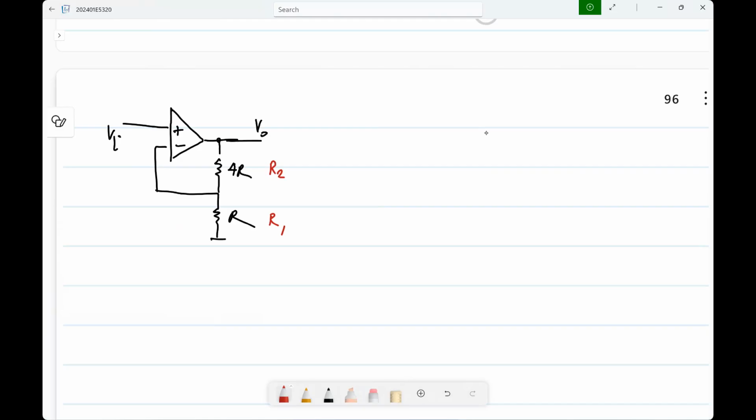No, this won't cause an offset. You can analyze it and see. This will only cause a gain error, right? This is not causing an offset. In the op amp, any mismatch in the transistors will give you a non-zero output current, even if there is zero input voltage. That is an offset. But the error in the value of resistors will not do that. It will give you zero output if you have zero input. Only if you have non-zero input, it will multiply it by some incorrect factor.